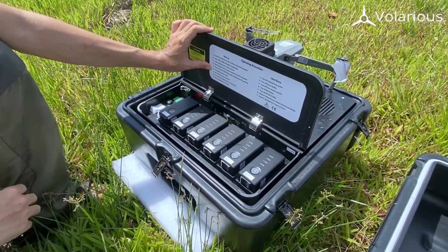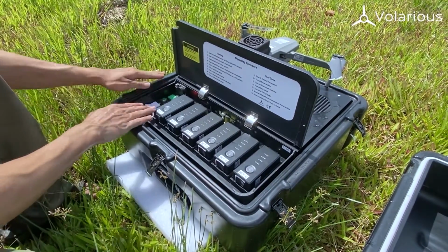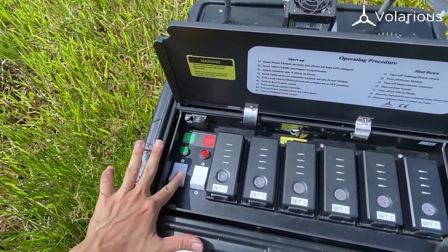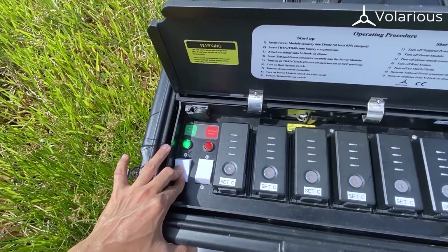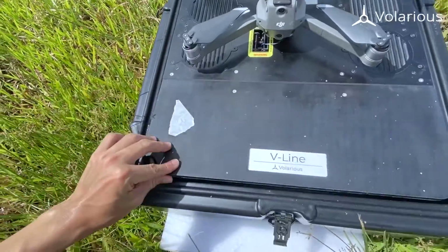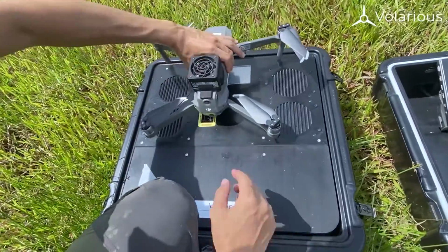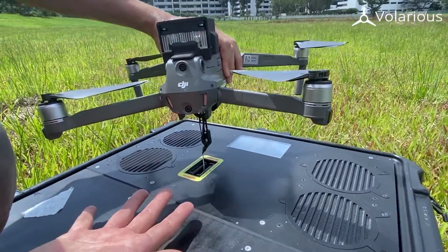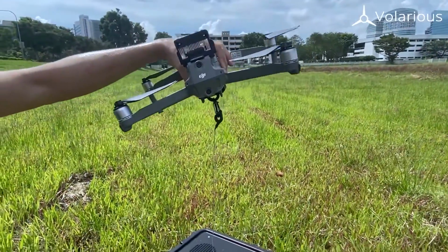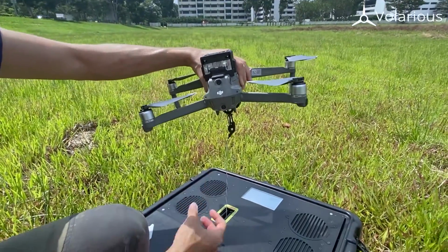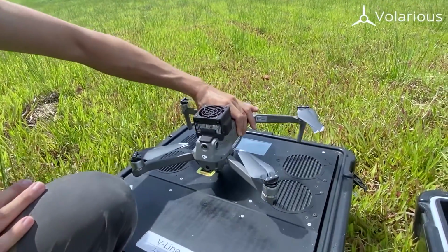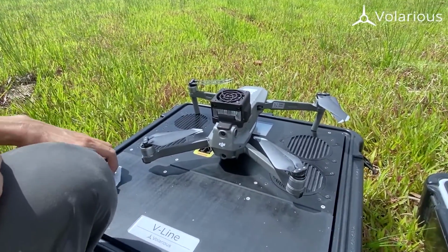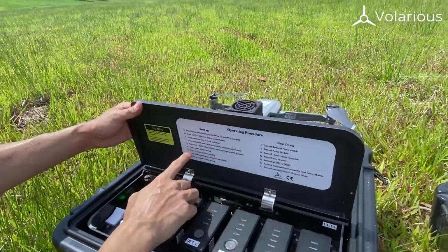Step 6, I'll proceed to turn on the reel system. So the power on button is over here, one for the reel, one for the tethered power. So now I'll turn on the green one, which is the reel system. As I turn on this system, the hook and the reel, the tensioning system on the drone will come online. So observe when I pull up and when I release, the system will auto tension for me and pull back any excess cable. So this is very important during flight. When the drone goes higher or drifts away, it will always pull back any excess cable. And this is step number 6.